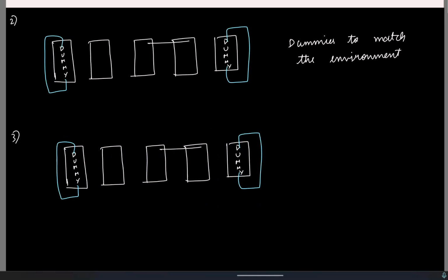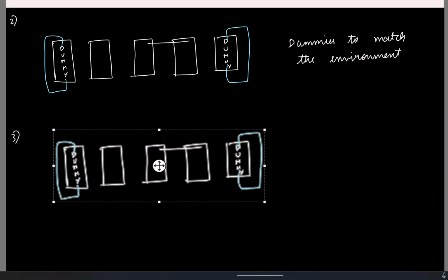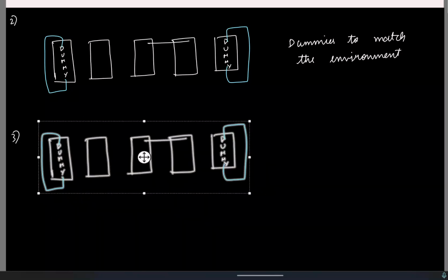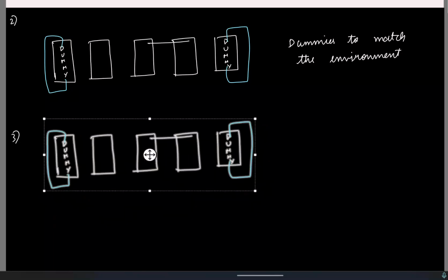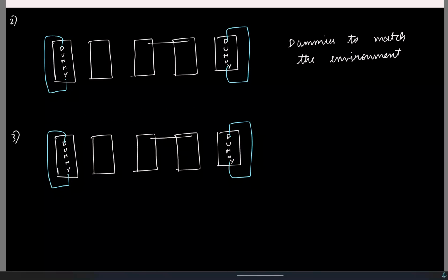So now let's say we have this guy. There is one other issue that can happen, which is this. It turns out in the fabrication process, during every step, there is going to be some gradient. That is, let's say you dope. So the doping concentration might have some linear gradient like this